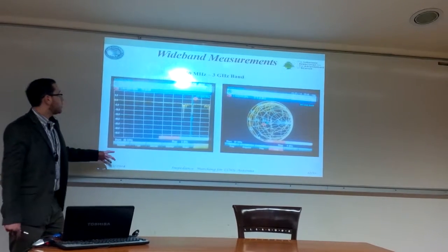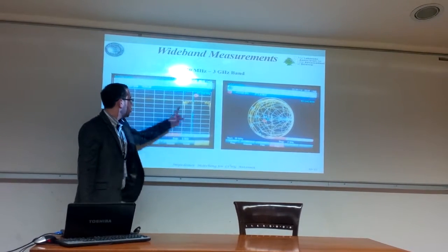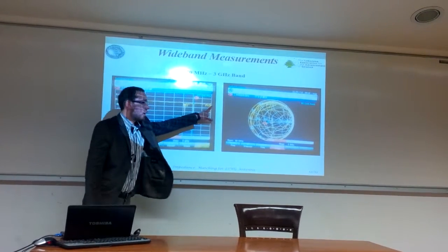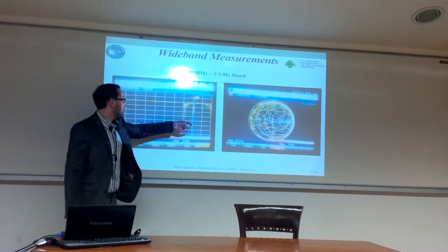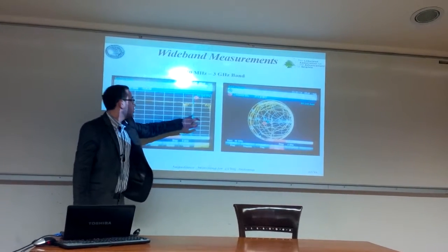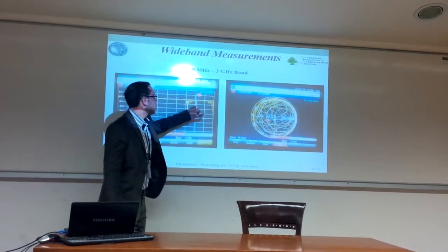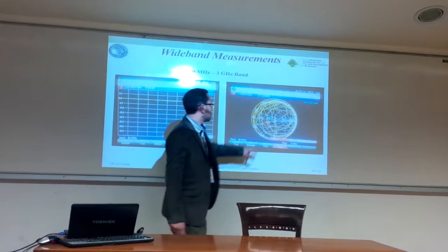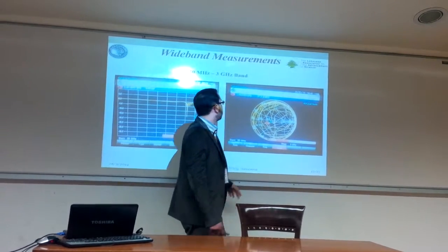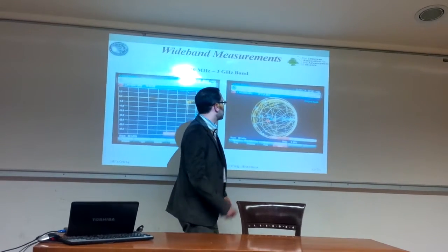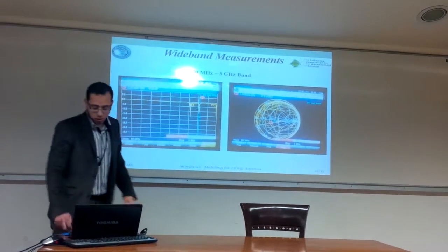And we can see here that our antenna is an S-band, so it only functions between 2 and 3 gigahertz. And we have 3 dips. It functions at 2.15, 2.44, and 2.85, and we are just in the 2.4. And you can see the Smith chart load, which is with a 57.3 real part and 4 as an imaginary part, which is near the center of the Smith chart.